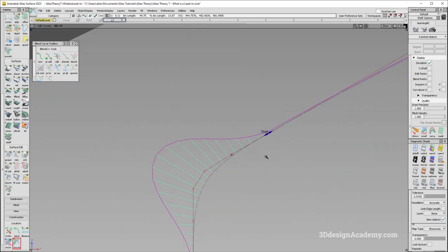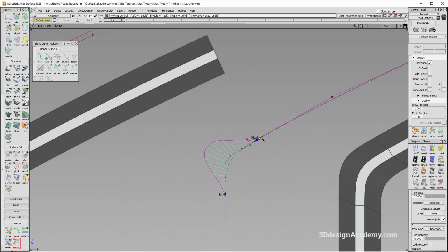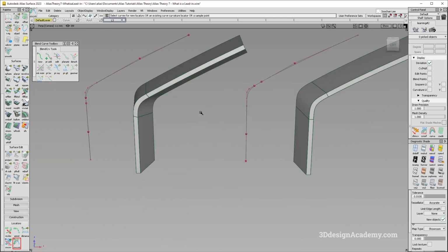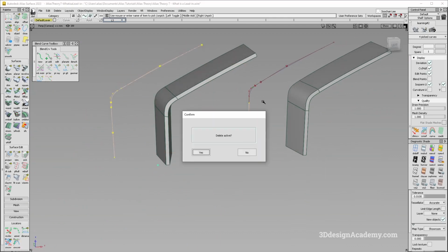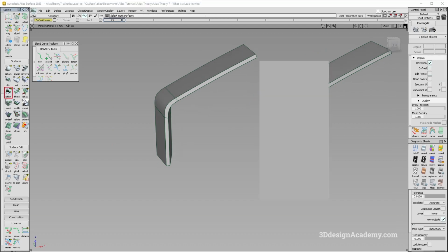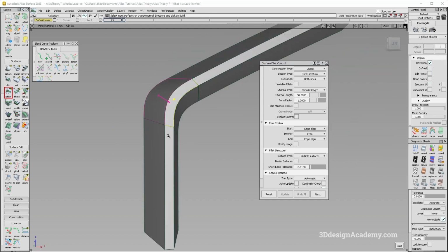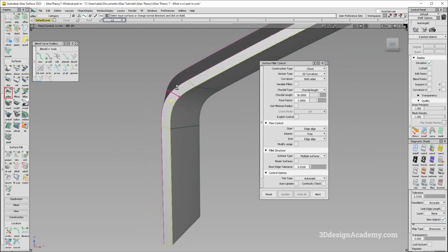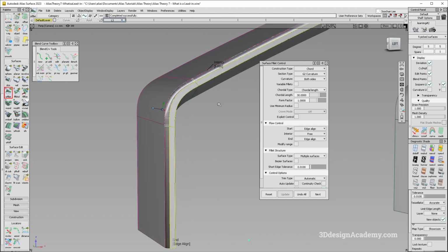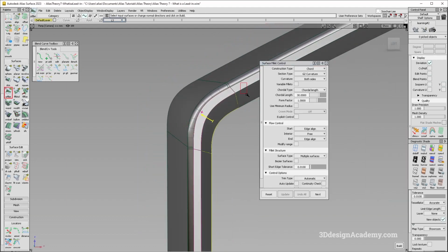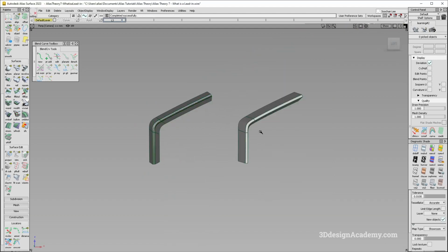Now this one, I probably have to scale down a little bit, and you'll see that the comb has a very nice transition. This might not seem like much, and the surfaces seem pretty similar, but if I put a fillet here, I think that might explain things a little better. So I'm going to put a quarter length of 30 fillet over here, edge align on both sides, and do the same thing over here, like this.